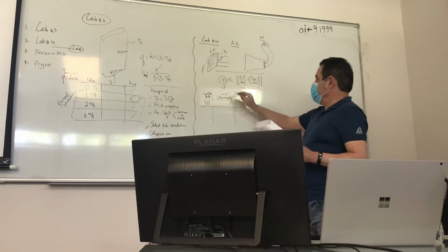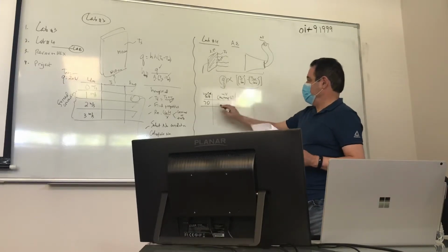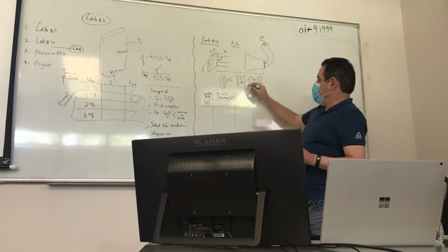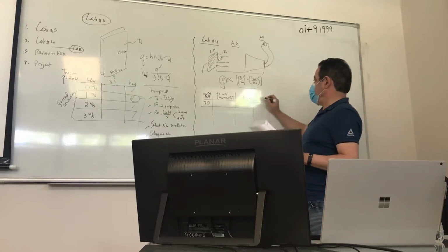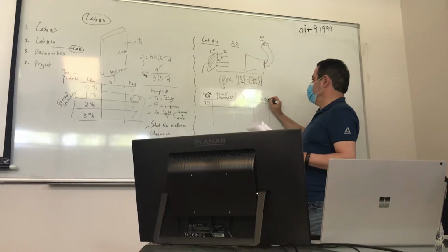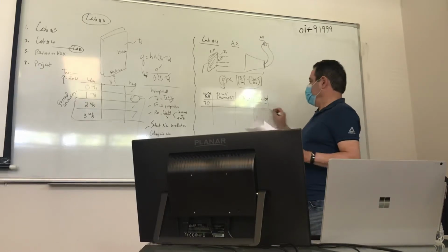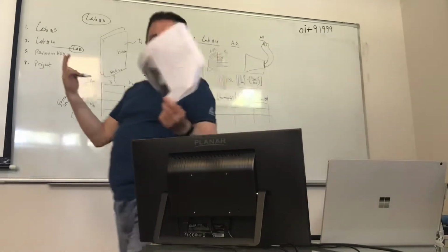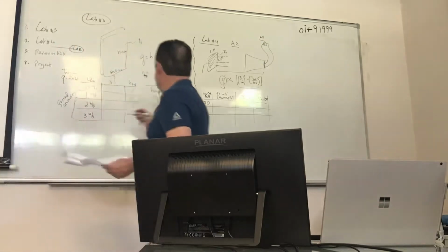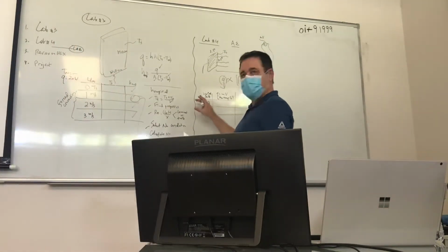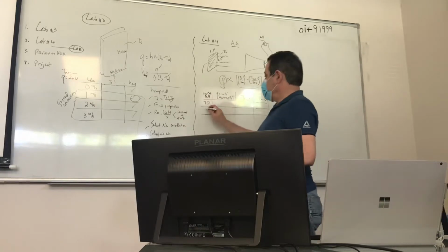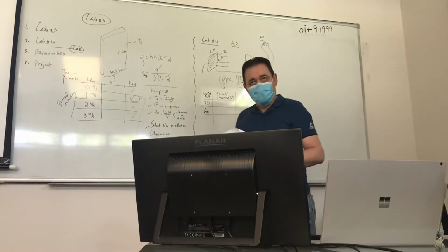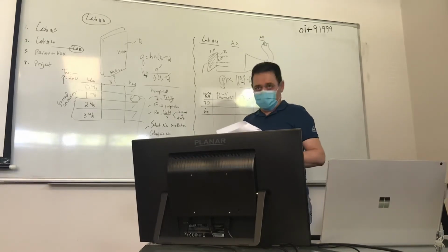Now, so you have Q, this is Q, essentially. Ts is known, and T surrounding is also known for each case. Because, you know, to figure out that they are proportional, you need to have at least 3-4 data points, right? So 70, then after we get the data for this, we're just gonna reduce the variac to 60. Then it's a big waiting game, okay? That's why I gave you the data for this one too, okay?